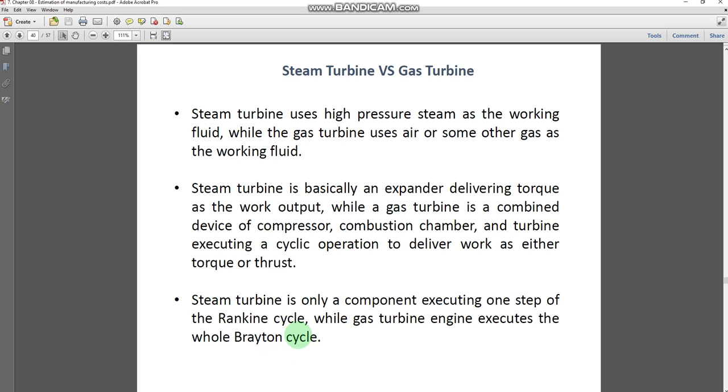The exhaust of the Brayton cycle is usually at a very high temperature, so you can connect it with the Rankine cycle to further utilize the heat from the exhaust gases and get more energy from the process. Whenever you see gas turbines in the industry, they are connected with the Brayton cycle. So you can have the Brayton and the Rankine cycle together, and in the Rankine cycle you would only have the steam turbines that would be used for producing electricity for the process requirements.